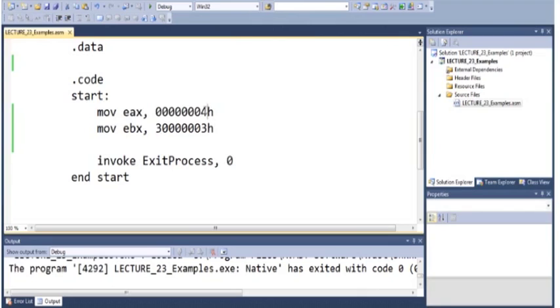We want to shift this EAX, for example, 4 bits at the left side, and these 4 bits which will be available here will be filled with the values of this EBX register, whatsoever the number of bits we are shifting. And if we use this EBX as a destination register, then its most significant 4 bits will be transferred to the EAX.